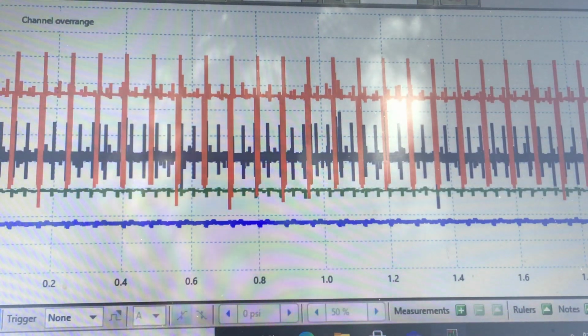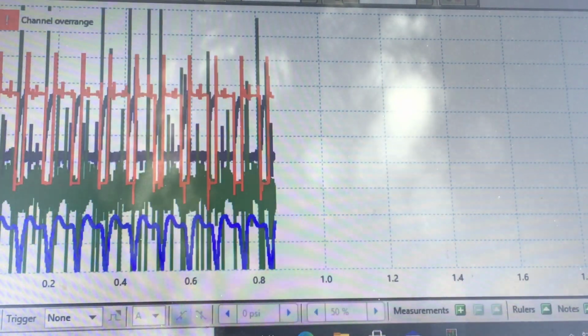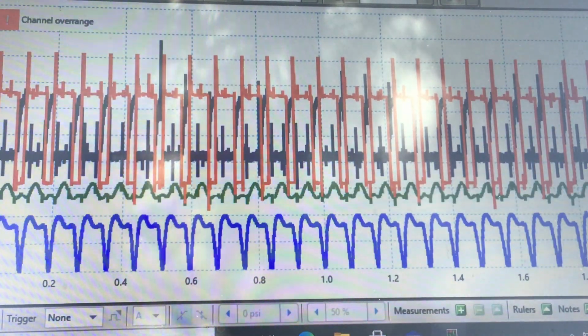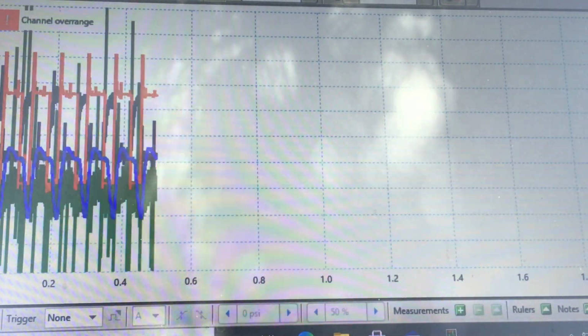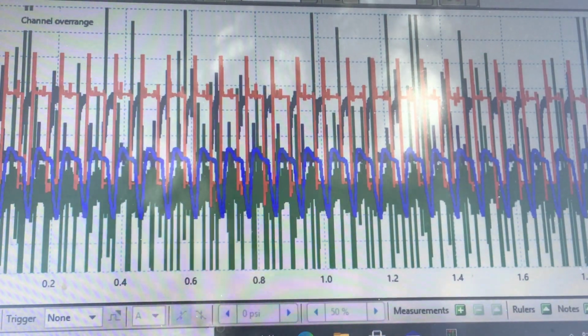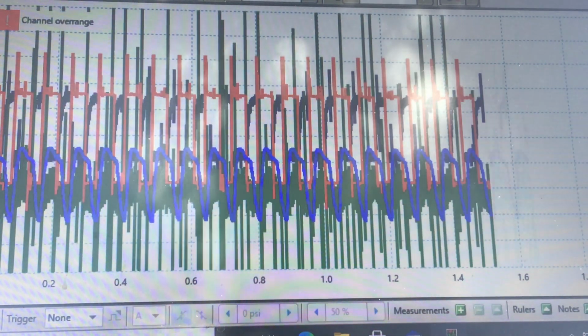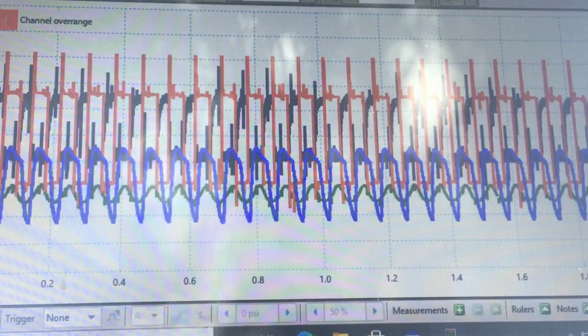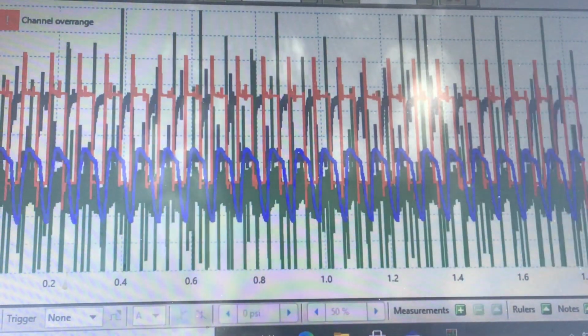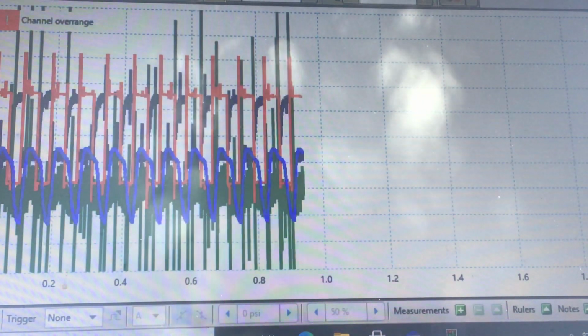So I'll go back, turn the scope back on, and we'll watch it, and things are starting to change now. Now we're getting up, it's idling. Evidently it purges at idle. We'll clean things up and stretch things and they'll look better. I'm going to give it some throttle and keep an eye on the 4 channels. I know green is kind of hashy. I will filter that when we analyze it. Let me give it some throttle.